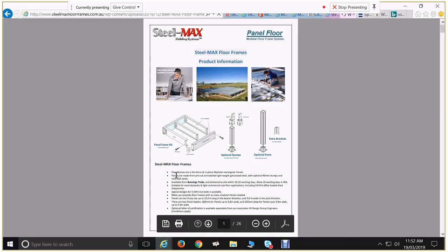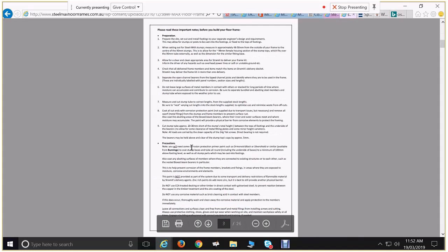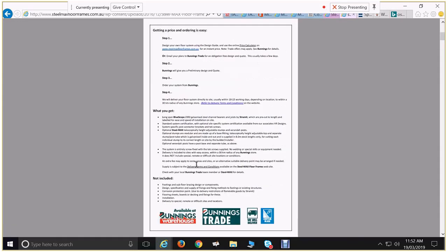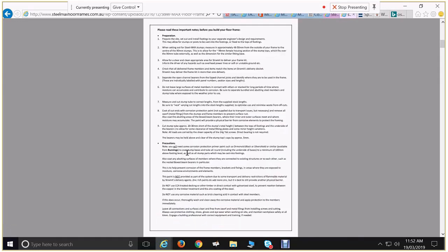Looking at that product guide, it tells you how it goes together. Keep flicking through. It gives you lots of information about the process of design or specification, but also about the limitations. So it says things like, you should not use this product within 300 metres of breaking surf. So you go, all right, well I can't use that for my beach house.